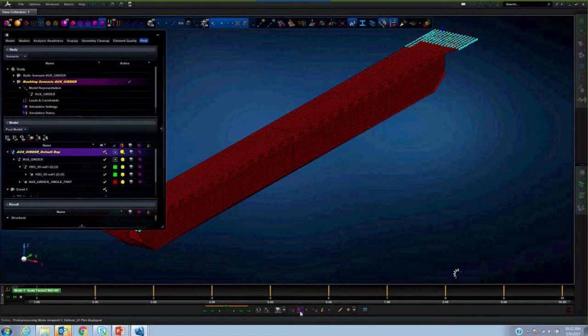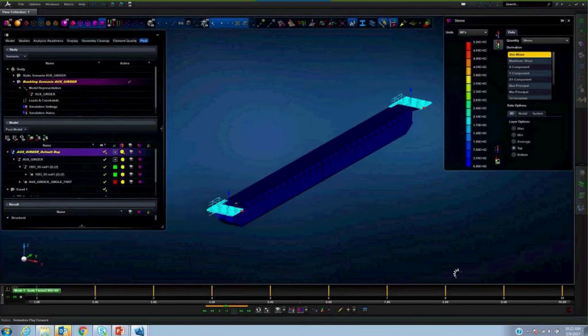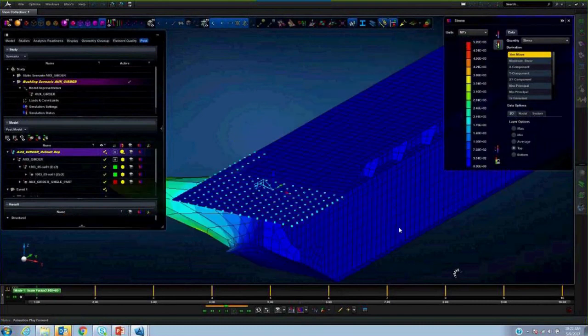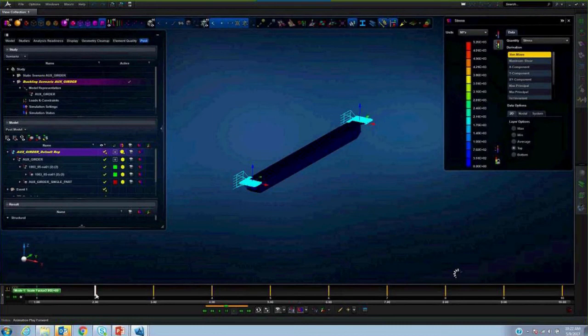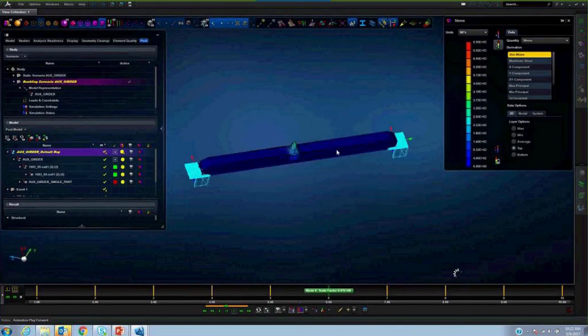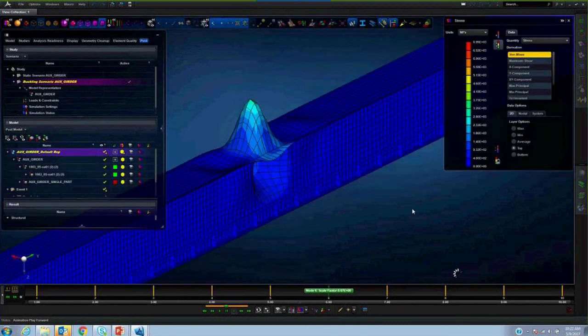Now, I can quickly look at what the buckling behavior is, and the first buckling mode is somewhere here. And obviously, this particular buckling mode is a spurious one because this part of the model should be connected to the rest of the model. That's the reason it is behaving that way. And the realistic buckling mode is probably mode number 5, not even that, probably mode number 6. Now you can see that seems to be the realistic buckling mode that's happening in the system, right?